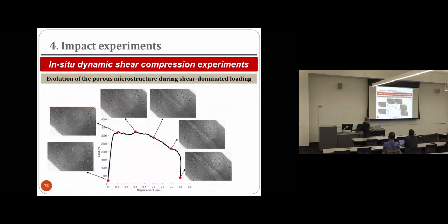So again, loading versus displacement, and this is the evolution of the porous microstructure. What we are doing now, but it's not over because this requires a lot of image processing, is to track at least some of the pores and to have a reconstruction of the evolution of the pores, and comparing also the analysis before loading and the post-mortem analysis of the specimen.